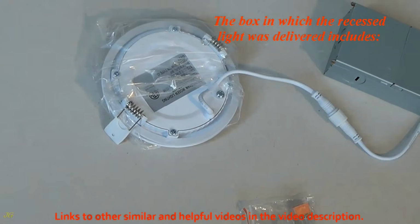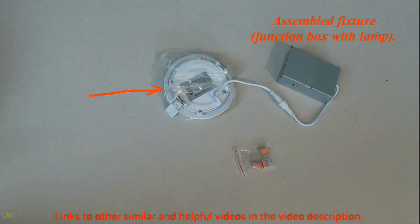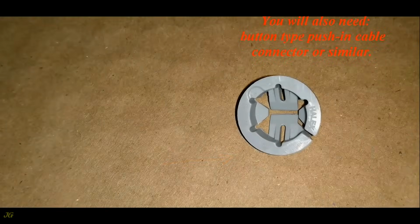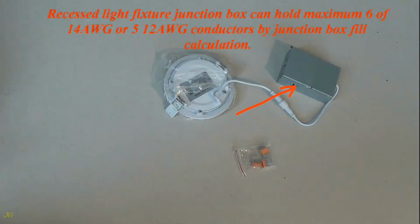The box in which the recessed light was delivered includes the assembled fixture, junction box with lamp, wire nuts. You will also need a button-type push-in cable connector or similar. The recessed light fixture junction box can hold a maximum of six 14 AWG or 12 AWG conductors by junction box fill calculation.